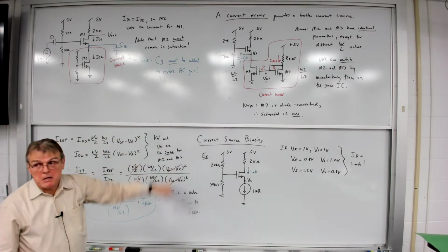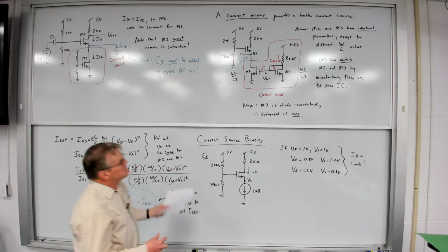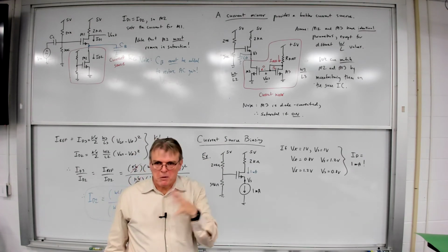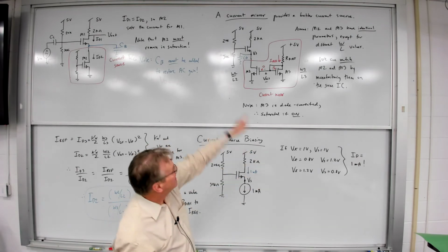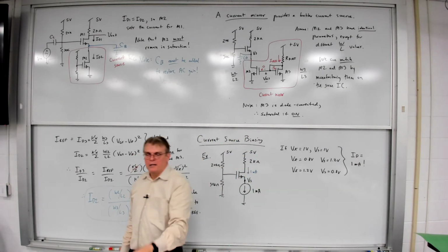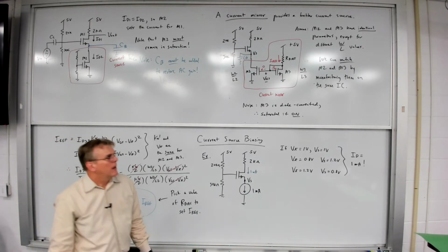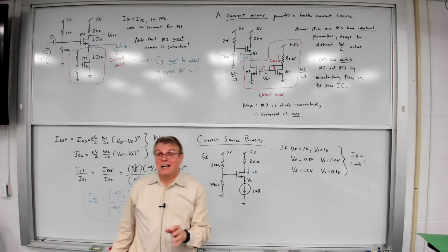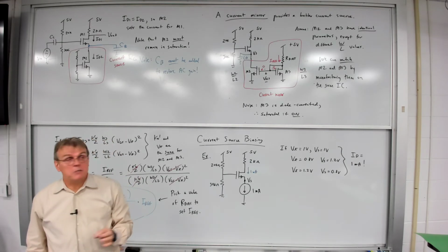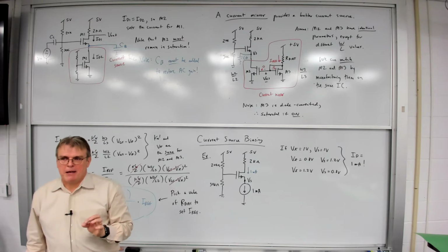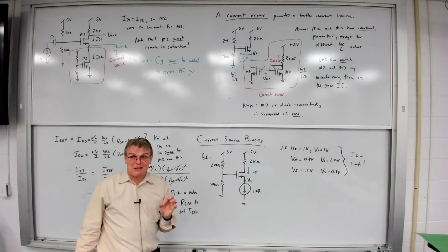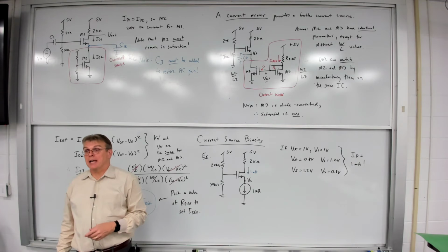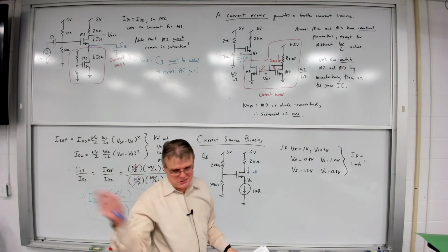We're not going to leave this current mirror technique behind, because it's worth pointing out to you guys, there is still something very wasteful I'm doing in this design. And what is that? I'm using a capacitor. I've got to use that big CB capacitor. It's got to be large in order to set the impedance of that source to ground. Wouldn't it be nice if somehow I could get rid of that capacitor? Well, we're going to come back to that later on. There are ways to have the advantage of a bypass capacitor without actually physically putting a bypass capacitor into the circuit. So we'll talk about that later on when we look at circuits used on integrated circuits, IC amplifiers. That'll be on the final exam and on the last homework assignment.